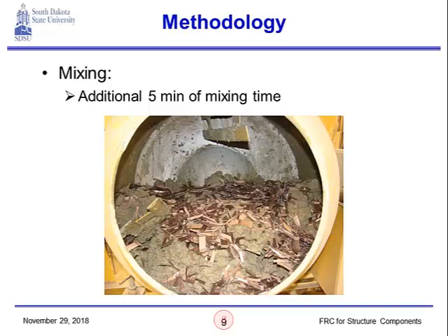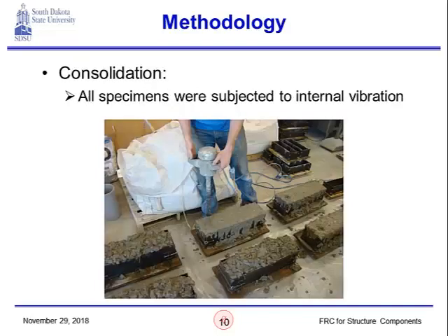But the only difference is that we had an additional 5 minutes of mixing after we added the fibers, to make sure we have a uniform distribution of fibers and to eliminate any kind of fiber balling that might happen. So that's the only difference that we had in mixing compared to conventional concrete.